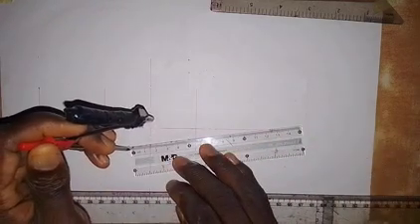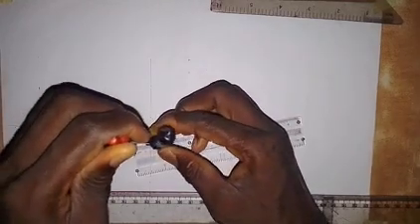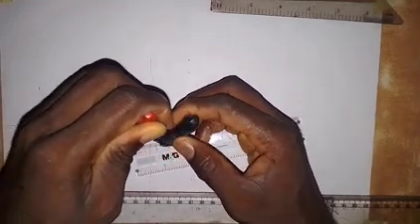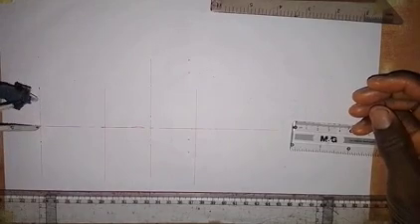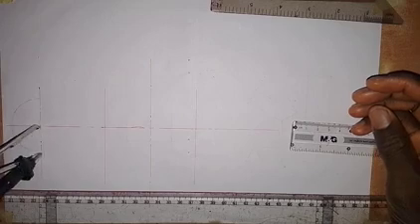The distance across corners for the horizontal prism is 50. So we divide 50 by 2, which gives us 25. We take that 25 millimeters and put the pinpoint here, and I'm going to draw a semicircle. That is what I need. So I'll just draw a semicircle like this.